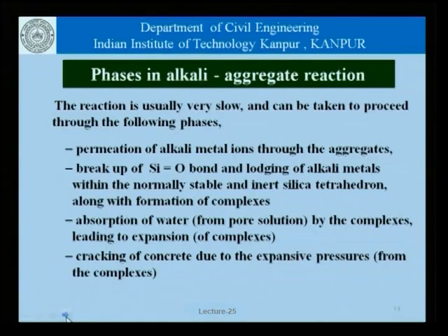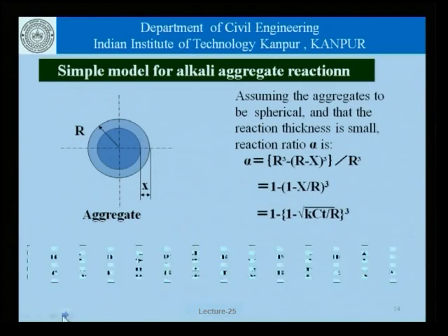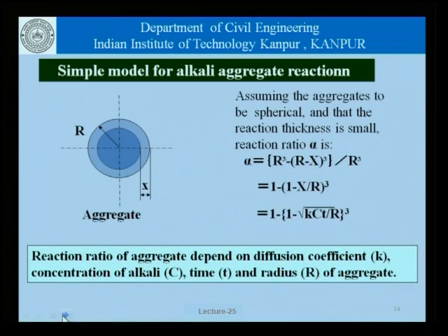And finally, of course, as we have seen, there is a cracking in concrete due to the expansive pressures. Now, if we look at the simple model of aggregates, we had discussed this slide briefly in a previous discussion, and we now recapitulate that discussion and put it in light with the model that we have just talked about. We are looking at potassium and sodium ions in the atmosphere or environment around an aggregate.